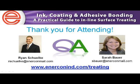I also note, too, dyne pens are great for quality control for operators. They're very easy to use. And we do have a link on our website if you are interested in learning more about how to use dyne pens and if you are interested in purchasing them, because they're a great way to see where you're at and where you need to be. And you can easily give, let's say, an operator a 50 dyne pen and know, hey, we need to be there.